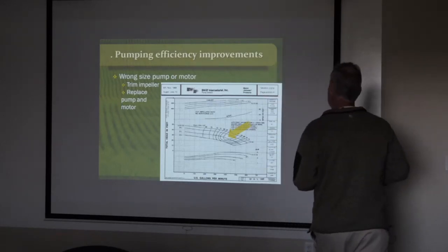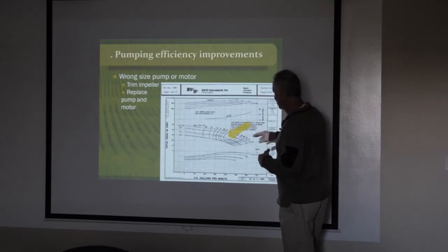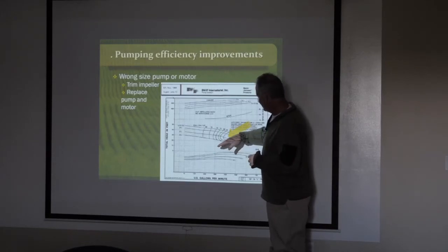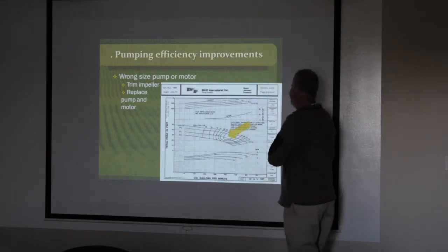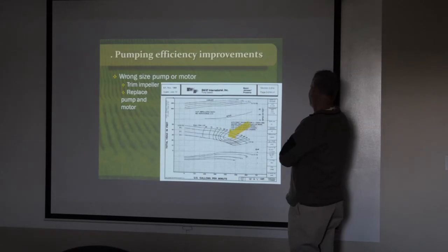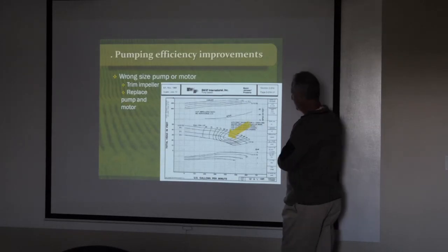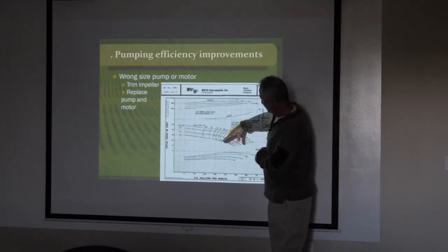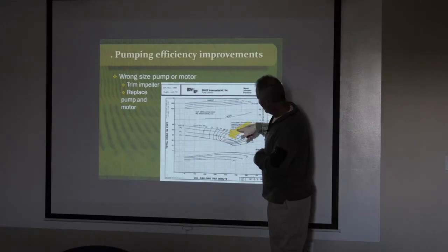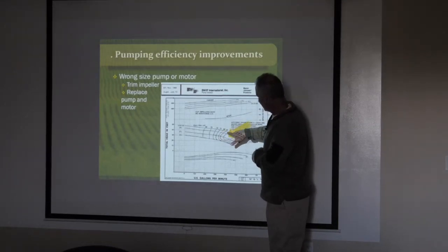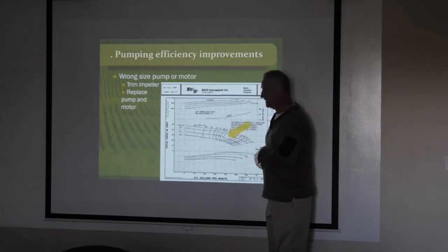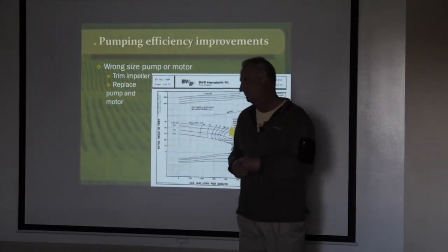And if we're able to move the system curve within this high efficiency area, then we can get energy savings out of this pump.